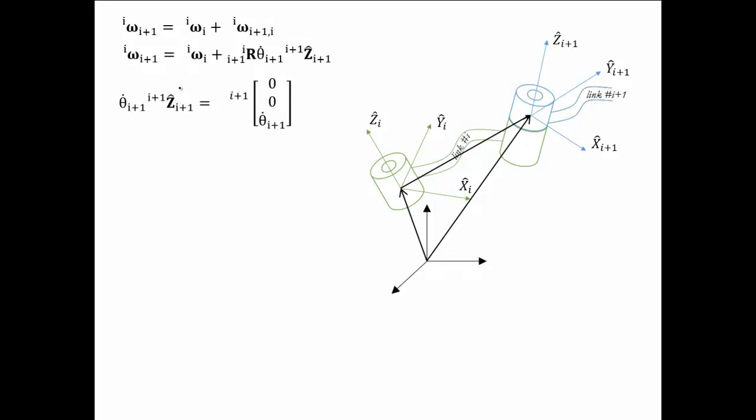So obviously this is along the joint, or omega we can say. So omega is always along the joint axis, and the joint axis is z. So z_{i+1} in frame i+1 only, which is actually [0 0 1]. So we can say that it's nothing but [0 0 θ̇_{i+1}]. Now this is something which can be substituted here, and then we can have the transformation from the i+1 frame to i, which will express everything in frame i.